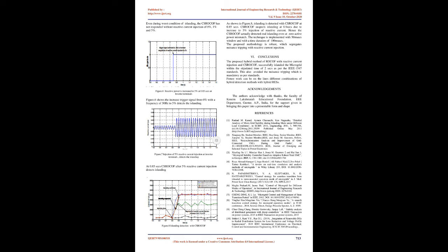But in this paper a low value of 1% of reactive current is injected with 30 Hz at Q-axis control of inverter at PCC. Precaution is taken to keep the reactive current injection value as low as possible so that the power quality is not deteriorated. This low value reactive current injection is not a matter when the active power mismatch is high.